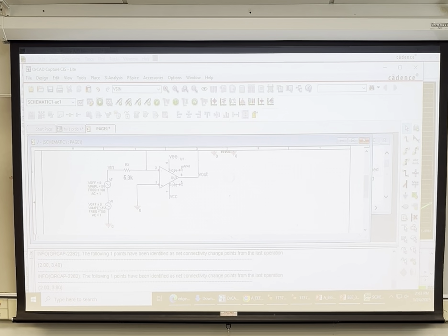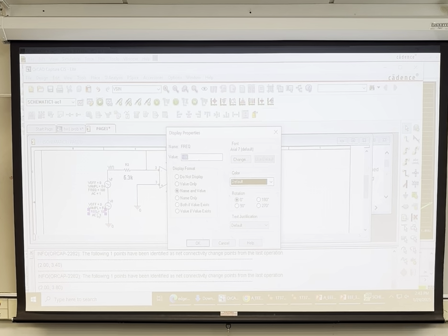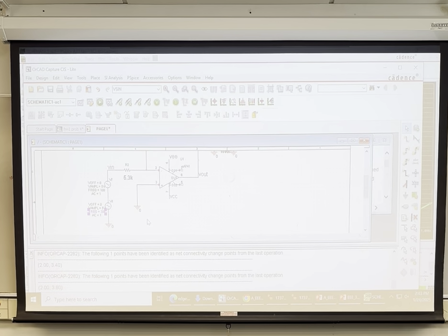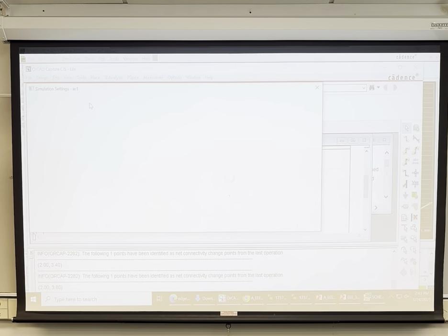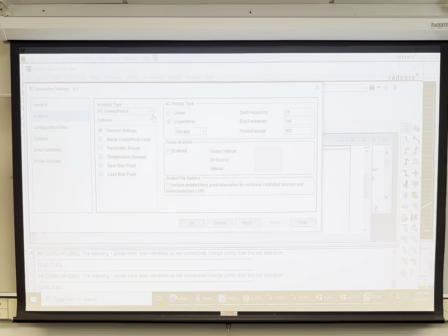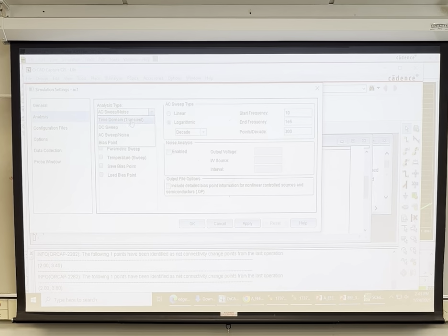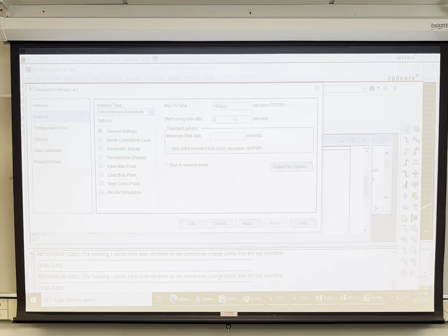And you can set this offset to 0. The amplitude is 5 volts. And what's this interfering frequency? 30 kilo. We'll set this to 30K. So we have two sources on the input for transient, both 5 volt amplitude. And now our simulation profile, you'll change that to transient.